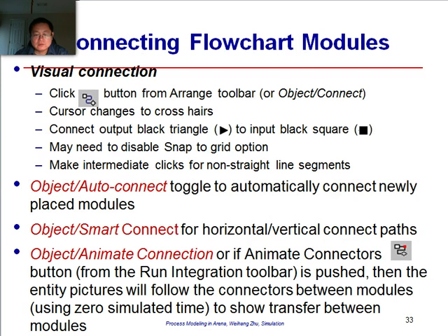You may have noticed that modules are connected by thin lines. To add lines, you need to first click the Connect button to enable the line connection mode. The option Auto Connect is enabled by default. With it enabled, when we add new modules into the flowchart view, connections may be automatically added.